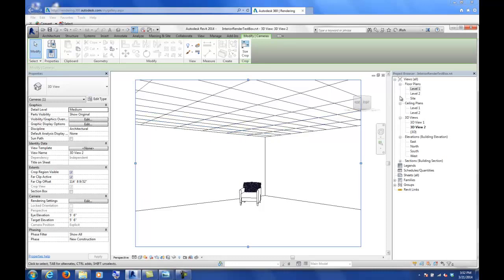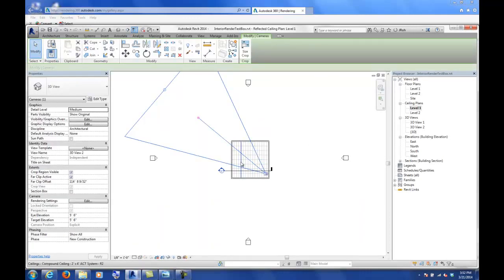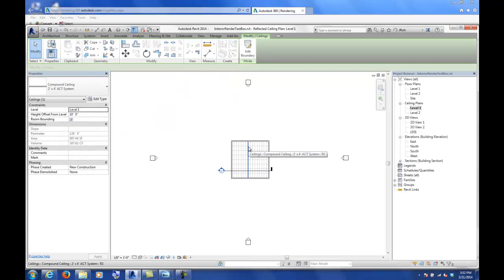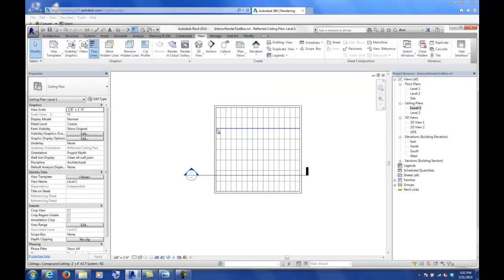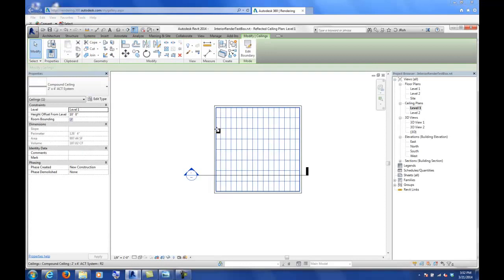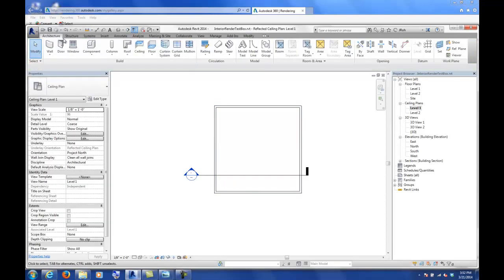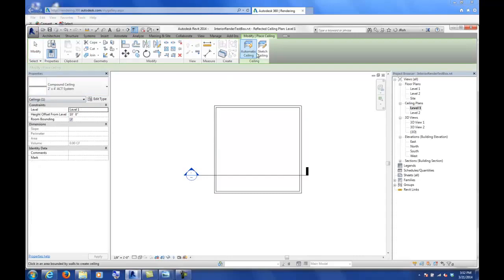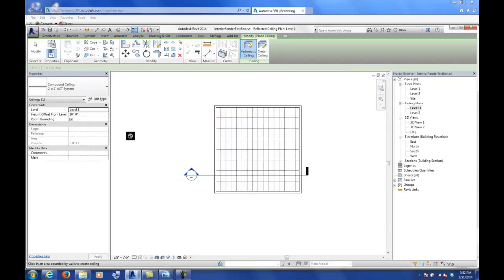Kind of. It's basically, if you're in a ceiling plan, I'm going to change this out a couple times. Let's delete this. I'm going to tab over till I can select the ceiling and delete it. If you go to Architecture and Ceiling, again, you can place it by Automatic Ceiling, or you can do a Sketch Ceiling. I should be able to hover over with Automatic Ceiling and just place it, whatever grid in there. That's basically it. You point and click as long as you have an enclosed space. If you don't, then you'd sketch the ceiling. And we went over in a previous class or workshop how to tilt that ceiling up if you wanted to, and so on.